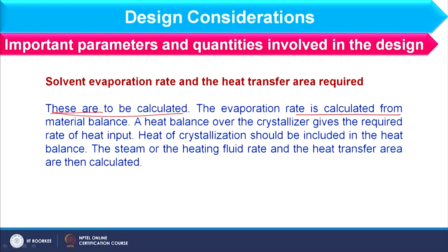The evaporation rate is calculated from the material balance, because how much feed is entering, how much crystal is formed and how much vapor is generated, all that we can calculate by material and energy balance, and this point we will also consider in detail when we discuss the design of the crystallizer.